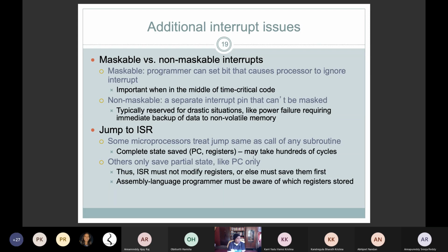Brown-out means when the power is switched off, generally you have supercapacitors on the board. If you look at the board which you have purchased, there will be supercapacitors. Whenever there is a power off, the supercapacitor is slowly discharged. When it is discharging from 5 volt downward, this interrupt will be enabled. That is called brown-out detection, and it will save the contents.